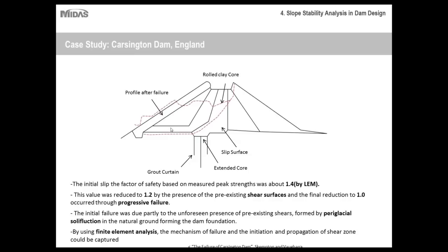That's why this particular case study is so important, because seepage analysis and slope stability analysis are very linked when it comes to dams and embankments. One thing to keep in mind is that when seepage analysis is used in a coupled analysis with either the limit equilibrium method or the shear strength reduction method, then you can get results that are more accurate and that safely take into consideration pore water pressures or changes in pore water pressure.